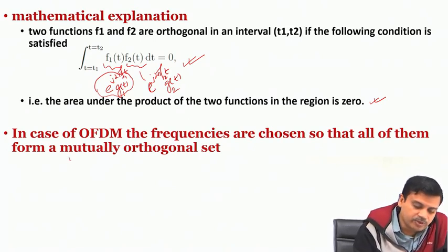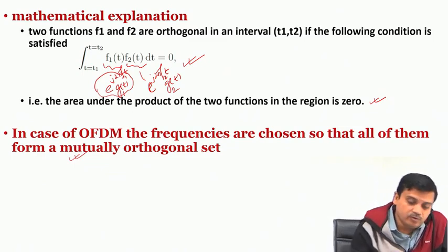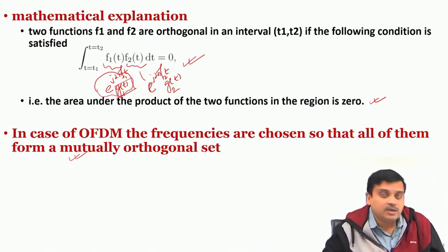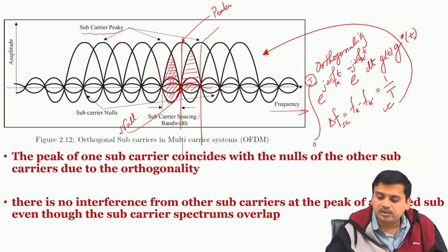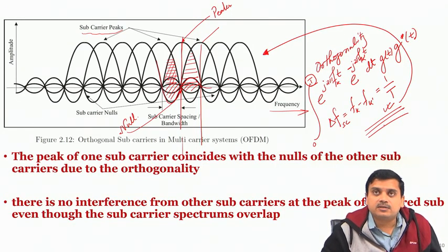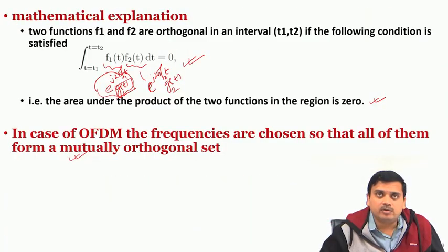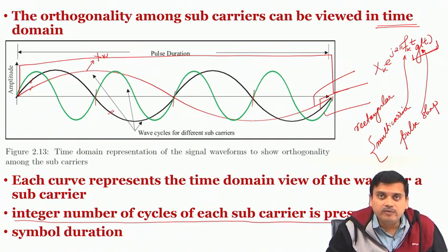We have also discussed that in OFDM the frequencies are chosen so that they are mutually orthogonal, but I will always remind you to recall that we have chosen G(t) to be 1 in all the expressions. Only then have we got this criteria, otherwise the result changes. This remains constant for all the OFDM. All discussions that we think of for OFDM would be valid only with G(t) equal to rectangular, or not changing within the period of interest.